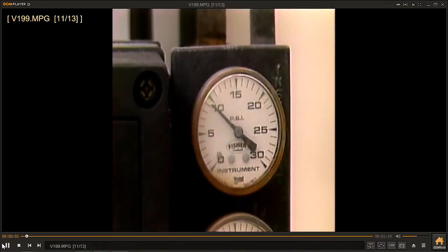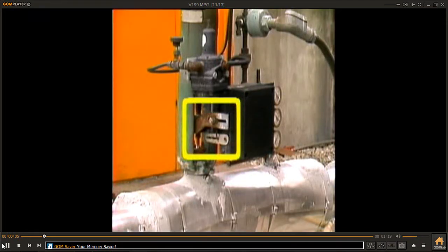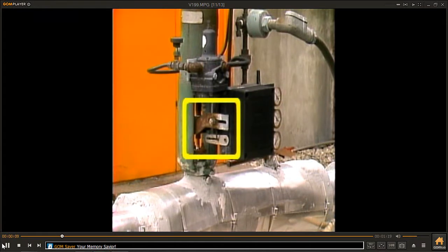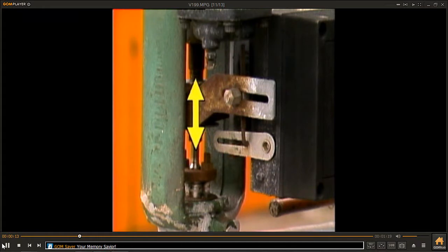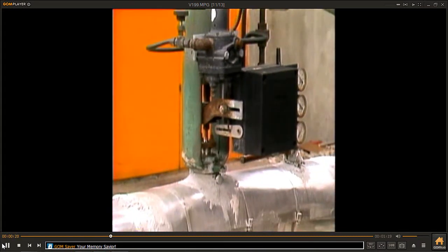The third gauge indicates the input signal pressure from the controller. A mechanical linkage joins the actuator stem to the positioner. This mechanical linkage may also be called a feedback linkage. As the actuator stem moves up or down, it also moves the linkage. The position of the linkage indicates to the positioner when enough movement has occurred to correspond with the air signal